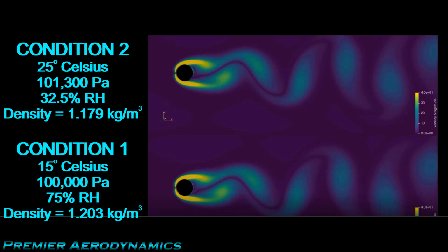98,000 and 103,000, which is a very typical operating range. And let's say that the humidity is 30% or 32.5%, let's say. If you calculate the density from there, again, these are all very typical conditions, the density is actually 1.179 kilograms per meter cubed, not 1.2. There's about a 2% error in your density now.